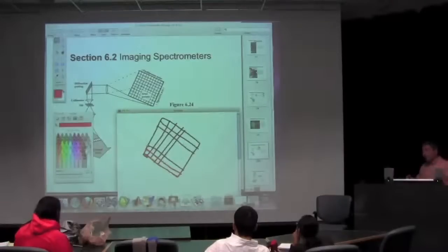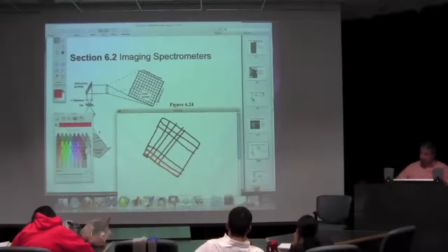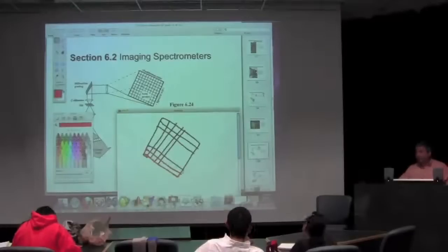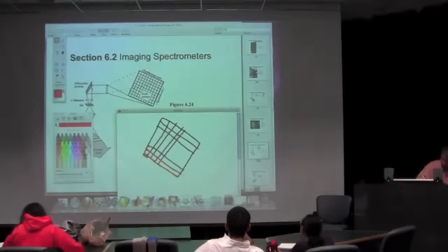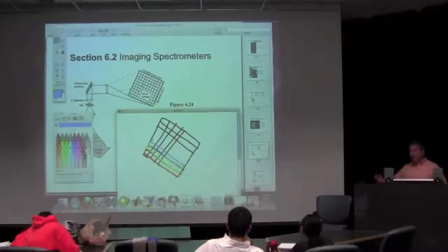so that the slit image comes right there, then what I'll do is I'll have a push broom system just like I had before, when I was just trying to use one band or collect one band of data. I'd have just a push broom. So this one line of detectors would sweep out this line on the ground, right? But because I'm also dispersing the data spectrally, I'm going to have different images of those slits at different locations on the sensor array.